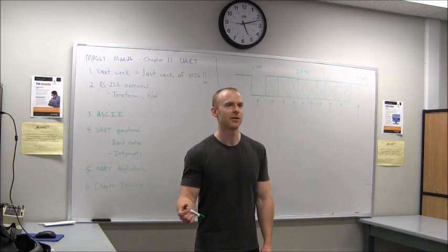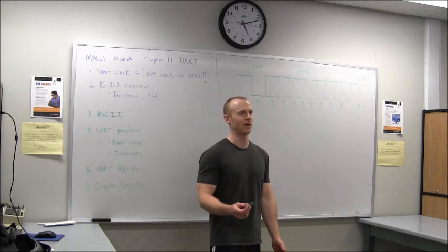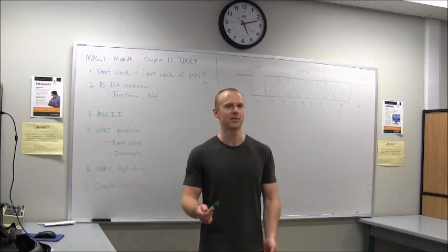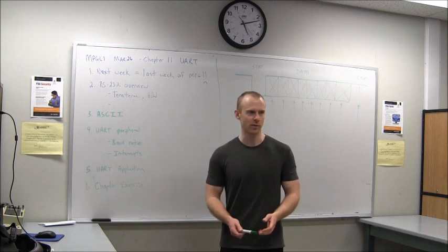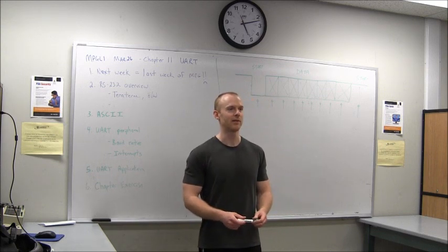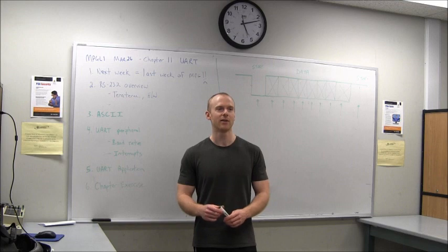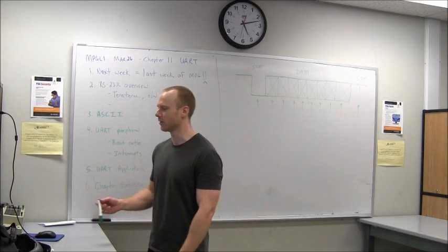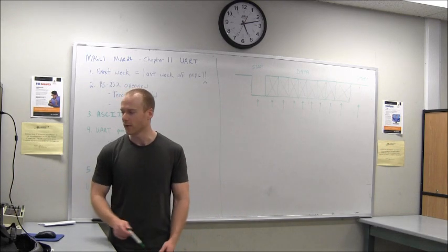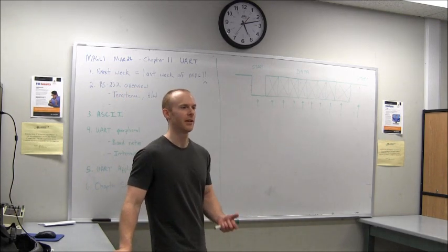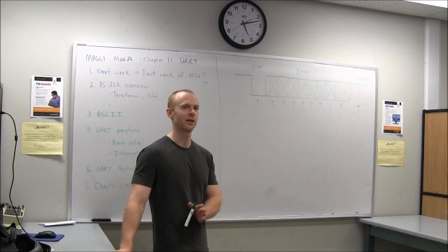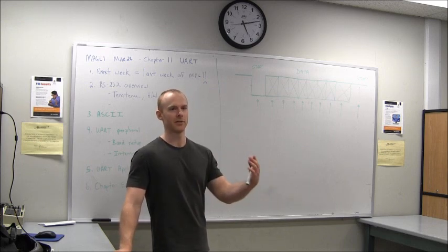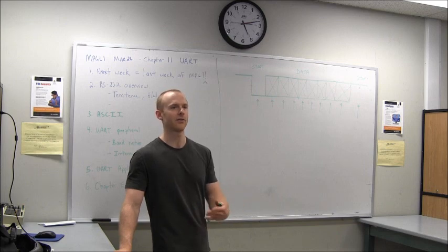So out of your computer, you come out at plus and minus, it's supposed to be 12 volts, but it's like 8 volts or something like that. Anyways, it's plus and minus something. And of course our boards are running 0 and 3 volts as our supply rails. So you have to do a level translation. And there's a little IC right near the UART connector that does that for us. It's a little charge pump circuit. So it ups the voltage and inverts it for talking out, but it also buffers it and down converts it to our logic levels from the computer.